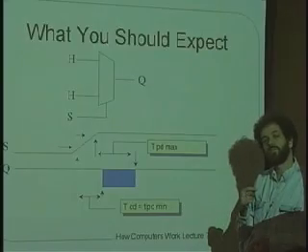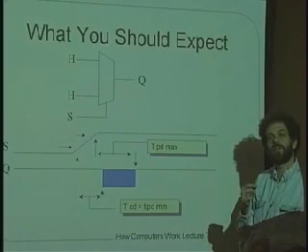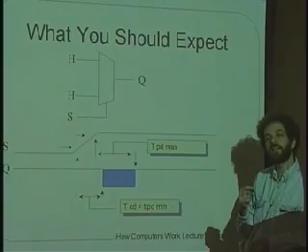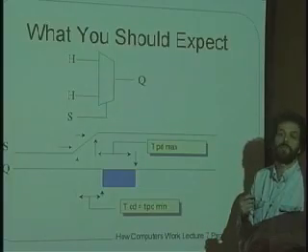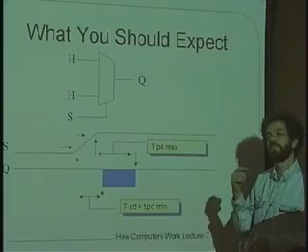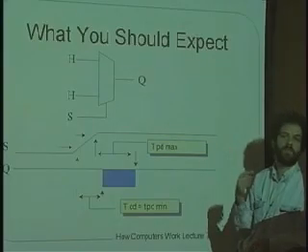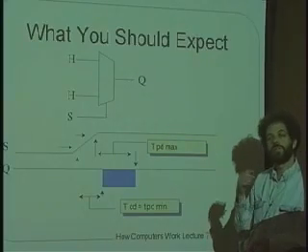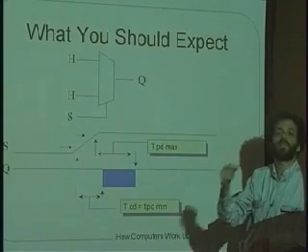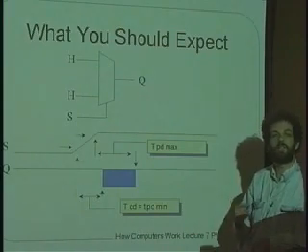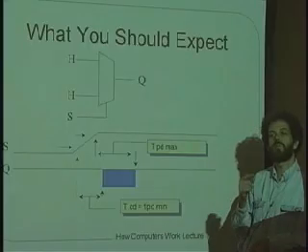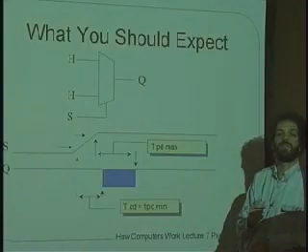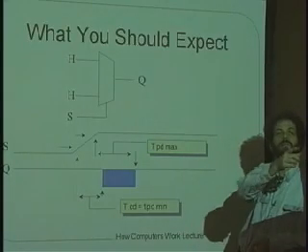What we care about mostly is how quickly will we lose the old data going around the loop. Whereas with propagation, remember how that was used. That was used to figure out how soon can I clock the circuit again and make use of the output. And there the question is, over the entire temperature range, over all kinds of different parts, over different data, what's the longest that it could take for the new valid value to get there, so that I know when to wait until I clock it the next time. So that's why that's in general measured in terms of the maximum.